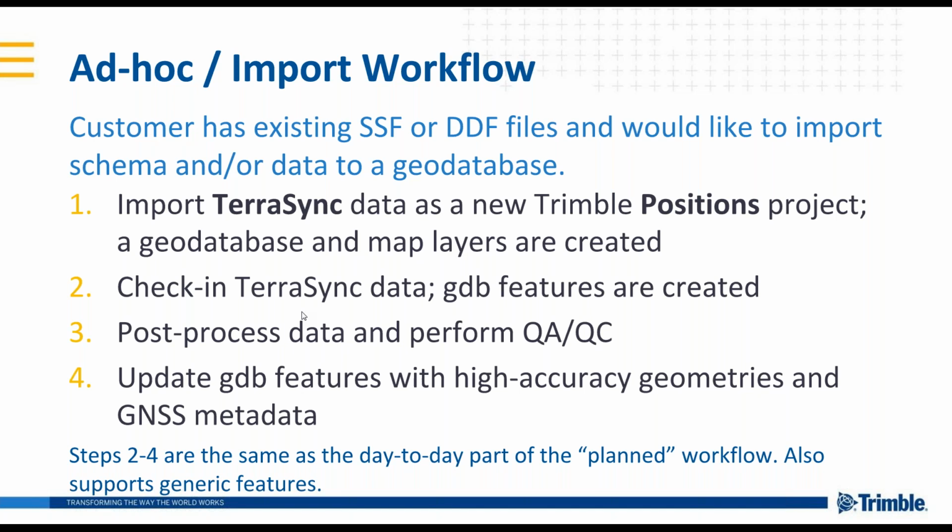What it'll do is it'll read the schema out of that SSF or DDF and create a file geodatabase and create new layers in an empty map document. You then have the ability to run through the normal check-in process. Check in the SSF, check in that data, it creates the geodatabase features, you can post-process, perform your QA/QC, and then update your geodatabase features.